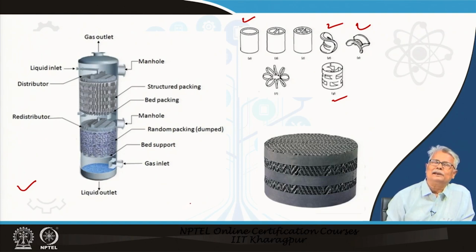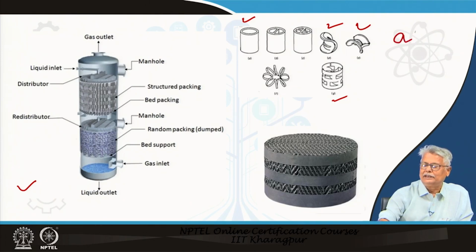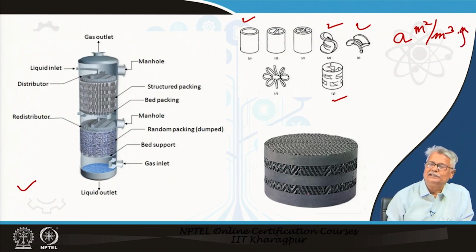What is the purpose of the packing? The purpose of the packing here is primarily to ensure the specific area, in meter square per meter cube, of the packed bed that goes up. What is the advantage you have? Ideally, if you have a packed bed, the surface of the packing should be kept wet with the liquid, over which or across which the vapor would flow.